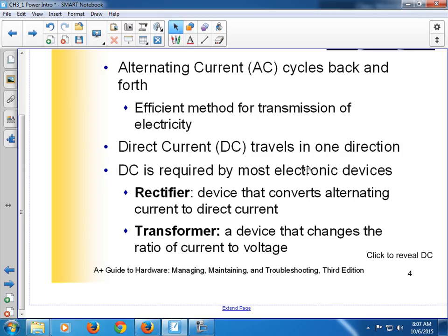Okay. So transformers or rectifiers change the AC to DC. Transformers lower the voltage. This is also a transformer rectifier. Okay. We get AC voltage coming in right here. That's 115 volts. Okay. And the biggest voltage that comes out on this side is 12. Between 3.3 and 12, we're going to learn which plug does which. Okay. But it not only changes it to DC, it also lowers the voltage substantially, which is one of the reasons these get hot. That's why these get hot.